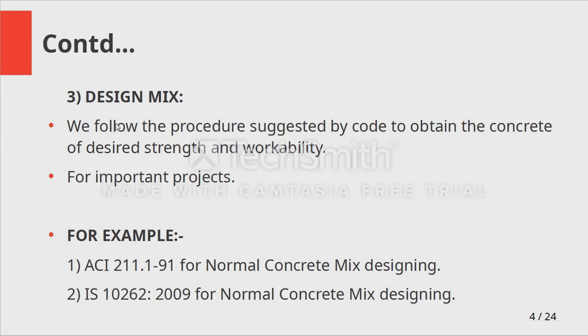So design mix is a very detailed procedure of finalizing your proportion. We follow the procedure suggested by a code to obtain the concrete of desired strength and workability. So either you can make your own standard, or you can follow a code to obtain the ratio for your desired strength and workability. And it is done for very important projects like shear wall, retaining wall. So for that kind of projects we follow this mix design technique, and we have different codes for that.